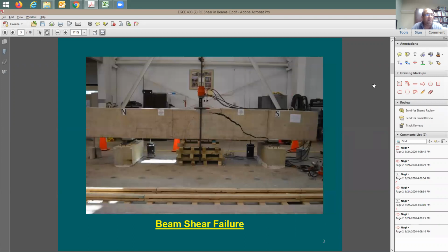So what happened in shear failure? In flexure failure, I'm going to put an arrow for the tension direction. Tension is going to be coming this way, and also this way, right? Now in here, where's the direction of the shear? I'm going to say here is the direction of the crack. Therefore, the direction of the tension is going to be like this, perpendicular to the crack. So at any location, you can say this is going to be the crack direction, roughly like this, and the tension is going to be perpendicular to it. So the question is, does the shear have an angle, or is the shear vertical?